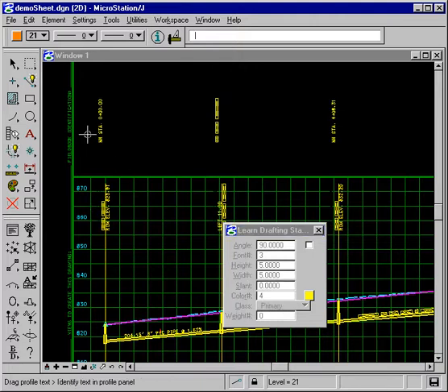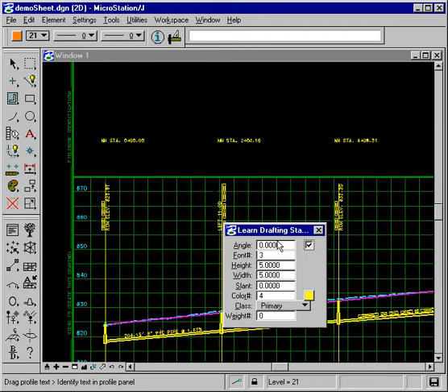Notice that all manhole stations have changed, not just the one piece of text. So all manhole station text, not only on this drawing and not only in this project, but this entire workspace, will now render like this. So next I'll select it and lock the text angle and change it to 0.